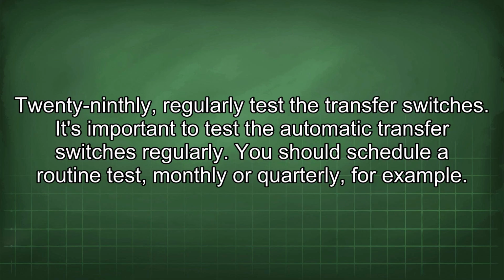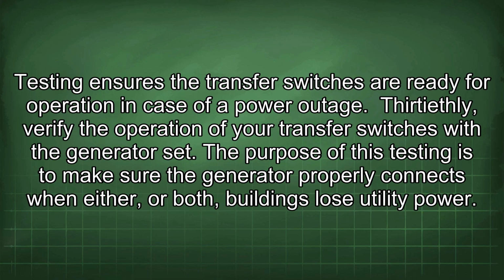29th, regularly test the transfer switches. It's important to test the automatic transfer switches regularly. You should schedule a routine test, monthly or quarterly, for example. Testing ensures the transfer switches are ready for operation in case of a power outage.